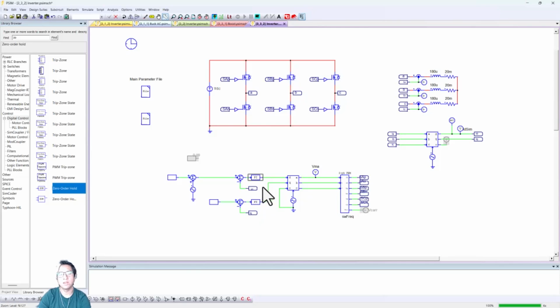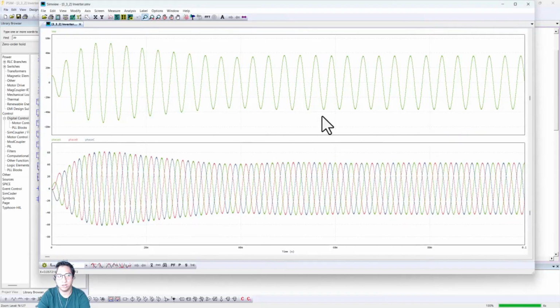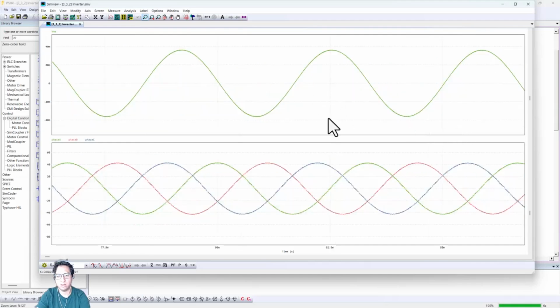So they were essentially two different controllers working very differently, and they had a very noisy modulation waveform. And the fix was just to copy and paste this one here, right? Or have the variables be in the correct place, right? So always be careful with that, because the previous waveform we saw actually looks very troubling, right? It doesn't look nice. So we might consider reaching out to support very quick. So yeah, this now is fixed.